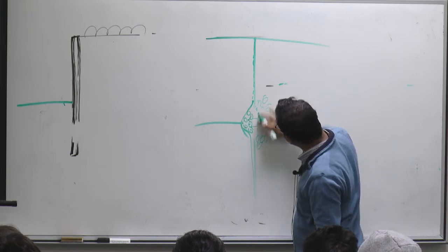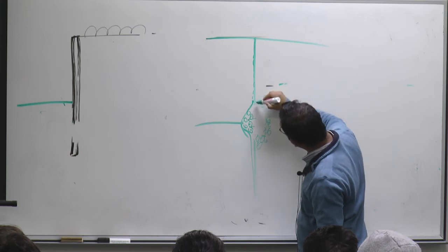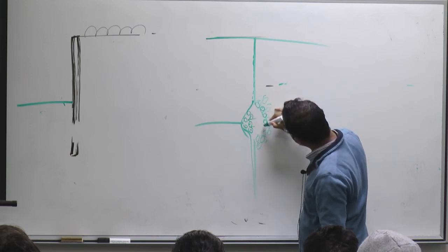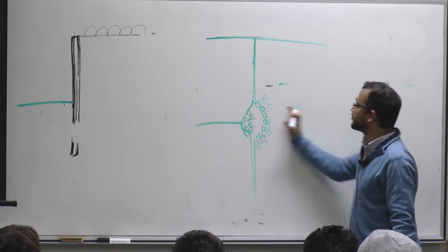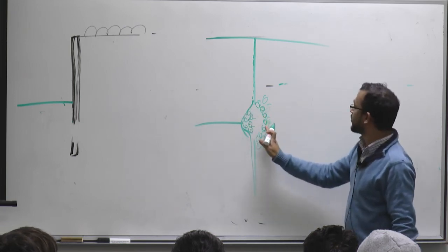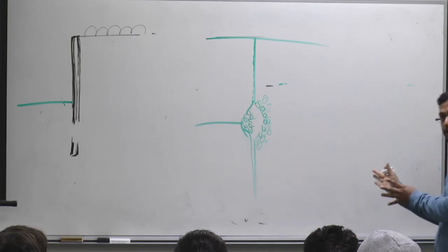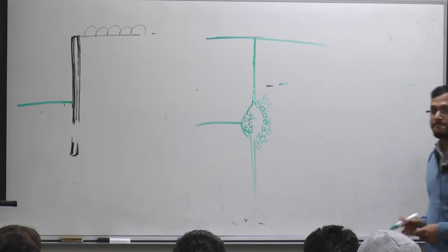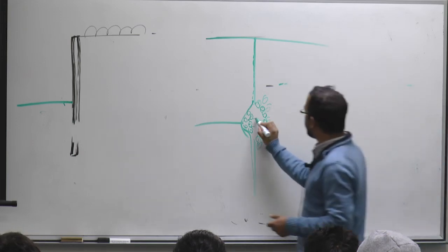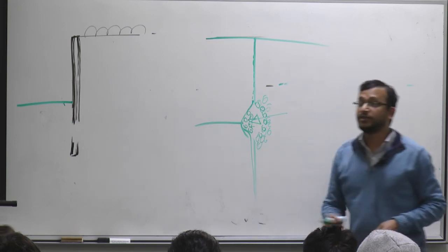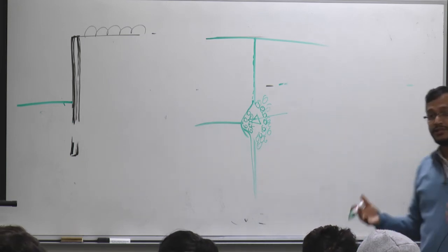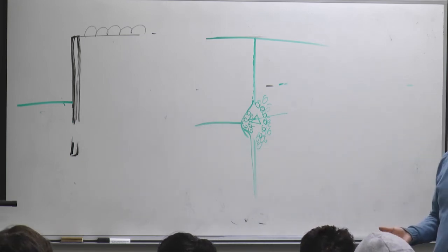But what happens is, at some point it will form a kind of arch. All of this soil will slowly move this side, but over here it will form an arch. It will hold the soil on our other side. So whatever the pressure is supposed to be there, it would not be there. The stress will decrease at that point.